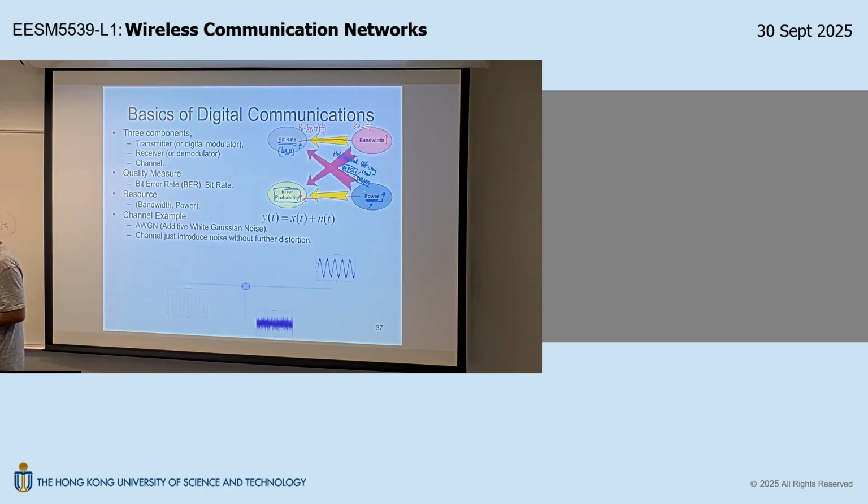Is that okay? That also explains why, for example, I'm not sure if you have ever paid attention to this detail. If you look at the specification of a Wi-Fi transmitter, the physical power amplifier for Wi-Fi is 1 watt, which is 30 dBm. But due to the back-off consideration, you notice that in Wi-Fi they have different data rates, different modulation. For BPSK, QPSK,